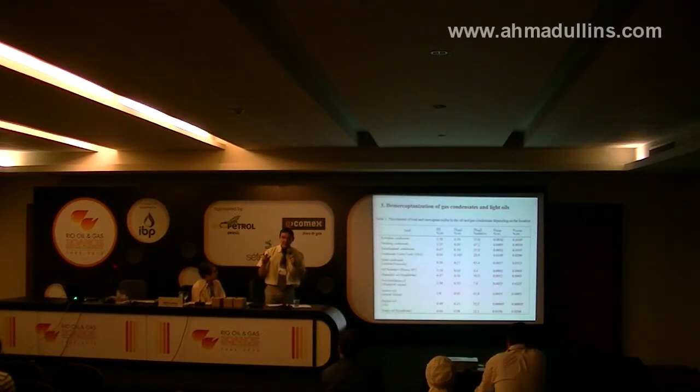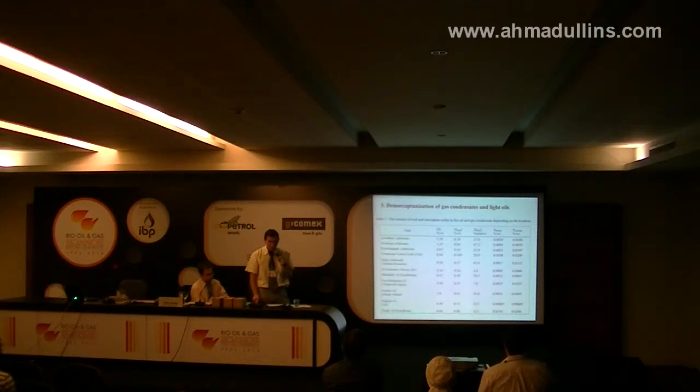The reason is the intense formation of coke deposits by thermal decomposition of mercaptans, with polymerization products of the decomposition on the catalyst. The share of this product is up to 60% by weight of coke deposits. These data indicate the feasibility of pre-sweetening high-mercaptan raw material before hydrotreatment.